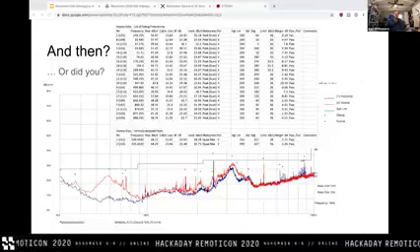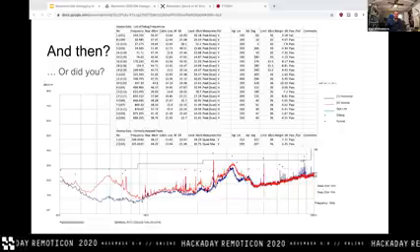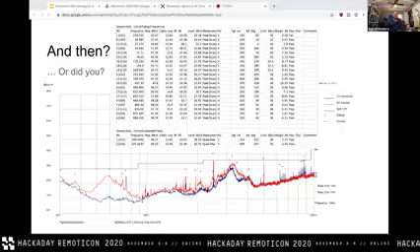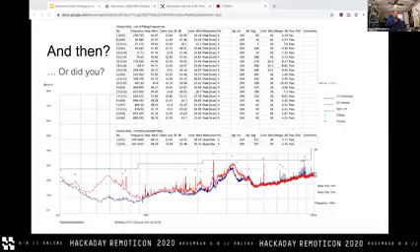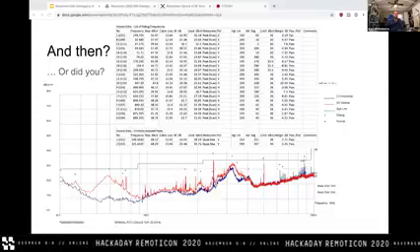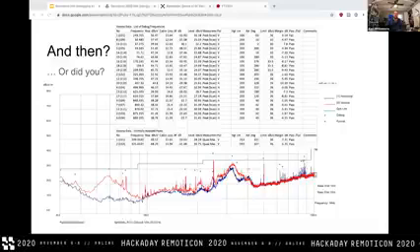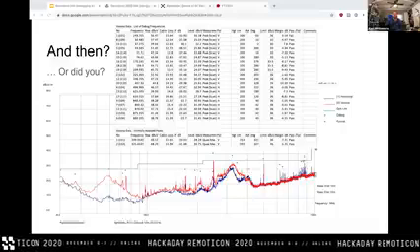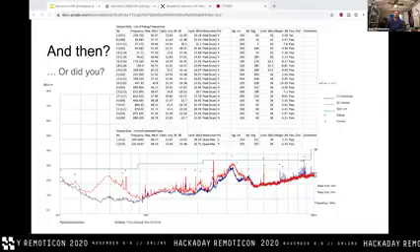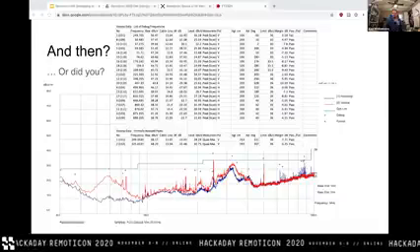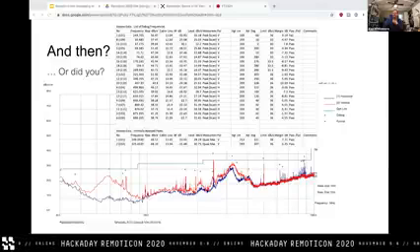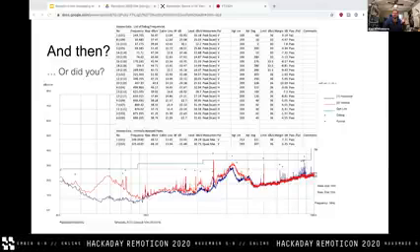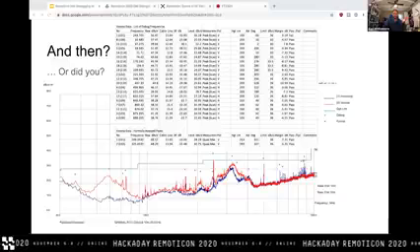So yeah, you have to be very careful about whether your test scheme actually exposes all of the potential failure modes in RF testing, and also make sure that your firmware isn't doing something stupid that it doesn't actually need to violate those. Which, speaking of contrived stupid firmwares, that's what we'll see later on the tiny FPGA, where, okay, this device is super simple. How could it possibly fail emissions testing?